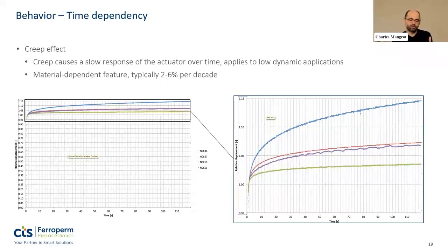So there is a decent margin in terms of voltage on a multilayer actuator. If you're using bulk, single-layer devices, then the limit will be much lower, because normally you will have sparks on the surface of the actuator. If I have time, I will go back to the construction of the different types of actuators.